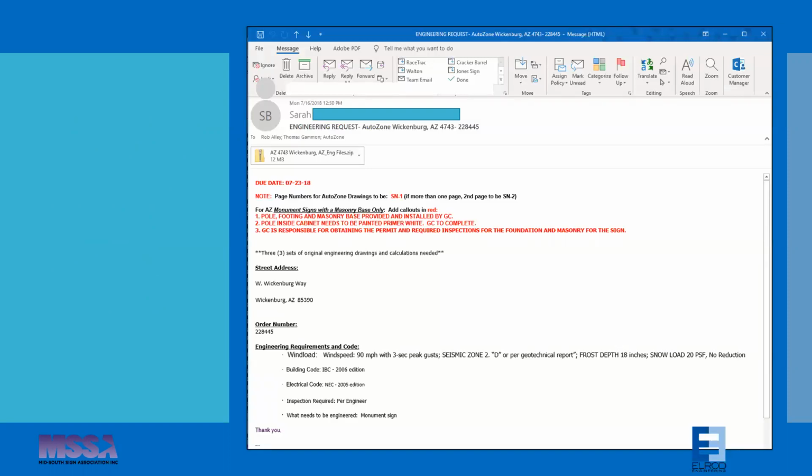The order form on the previous slide is actually attached to this email. I like to use this as an example because in a very condensed way, it contains a lot of information. There's a zip file that has a geotechnical report, artwork for the signs, building survey, photos, all that available information. In the middle, the street address. Lots of times that gets omitted, but we need to know the street and the city so that we can know the proper building code. And then down below, they've included what they know as far as specific code information from their code check. So again, that's helpful.